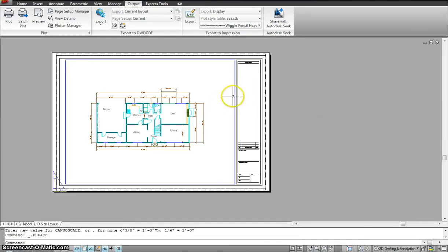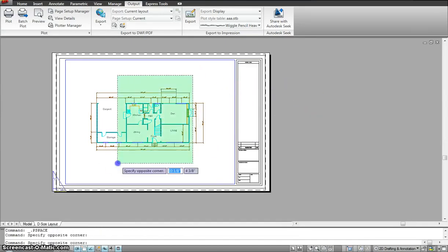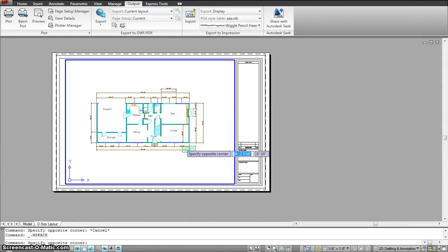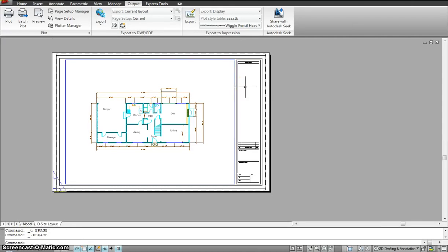And once I have done aligning the sheet, scaling my drawing, I will double click outside. Once I double click outside, again I'm not able to select anything in. Okay, the only thing I'm able to select is the title block. Why? Because the title block is in the paper space. So I could double click in, go there, modify it. Why? Because when I double click, I jump to my model space. But never modify from here. If you want to modify something in the model space, always go to the model and then do that. So I can double click out.